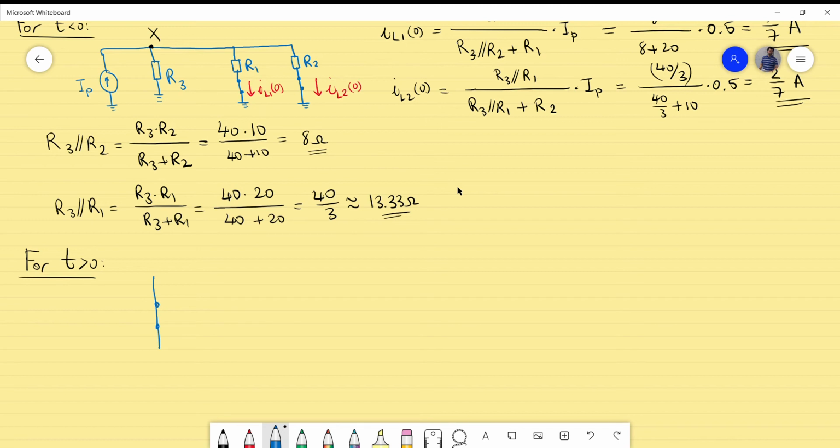I will just emphasize it with a short, and we have still our resistance and the short for the L1 and the R1, R2, and the short for the L2, but the stored energy in these inductors will flow through the R1 and R2 as described just a minute ago. So what we need is actually to determine the time constants after we know the final values.